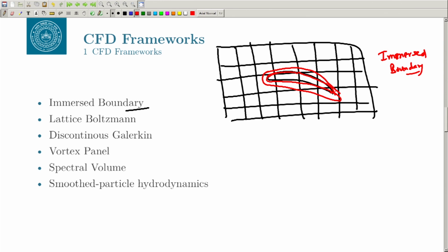Then lattice Boltzmann, okay, this has also become very popular for solving fluid flow problems, but there is a fundamental difference between lattice Boltzmann and what all I talked about till now. In the lattice Boltzmann, we use the lattice Boltzmann equation instead of Navier-Stokes equation. Okay. You know about the Boltzmann equations, and then you can basically, in the limit where your Knudsen number goes to 0, okay, or very small, use those equations on a lattice to solve problems of fluid mechanics, solve problems which are in continuum. Okay. So, these approaches are called lattice Boltzmann approach.